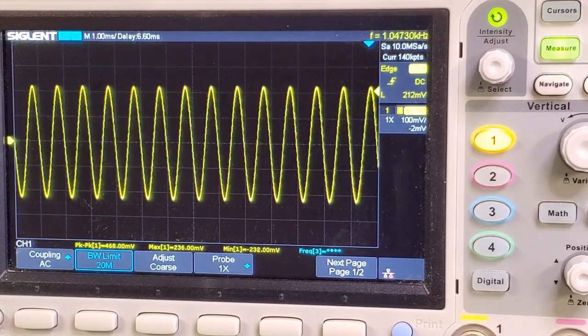Okay, so now I'm sending the audio output to the oscilloscope. It's now at minus 50 dBm, just so we could see the signal a little bit better. So I'm on lower sideband at the moment, same setup as before. The signal generator is emitting 14.2 megahertz. I'm on lower sideband and I'm tuned to 14201. So you can see there's that 1 kilohertz signal on the output as expected.